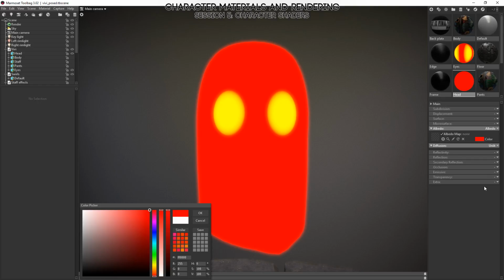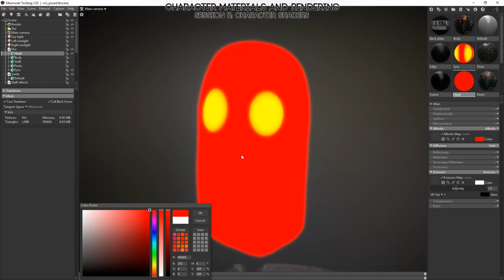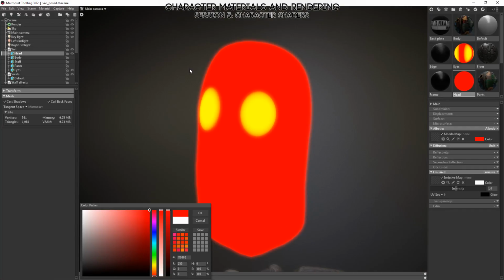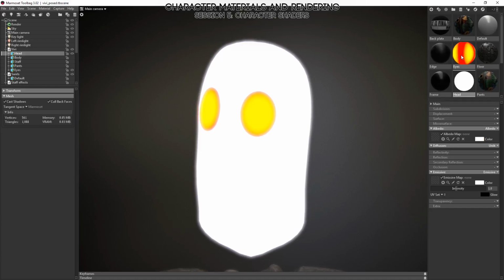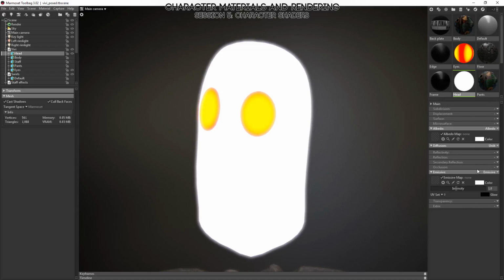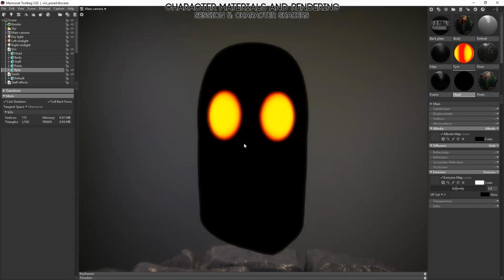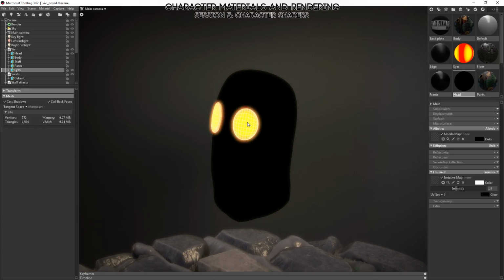It's exactly the same as using an emissive texture, except that when you use emissive, you can combine it with things like gloss and specular, and other types of shading. So flat shading is the same as using an emissive, except the emissive is only rendered as a part of the larger shader, whereas a flat shaded one is just simply the single flat pass. However, this is only really good for items that either are completely black, like you see here, or that glow.